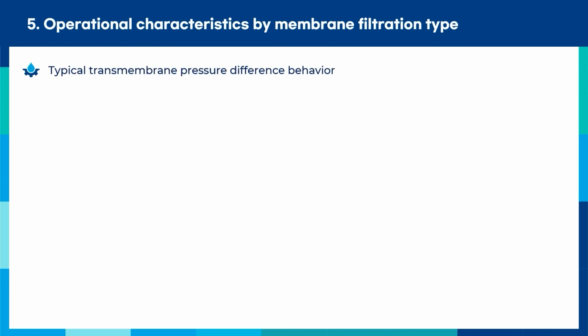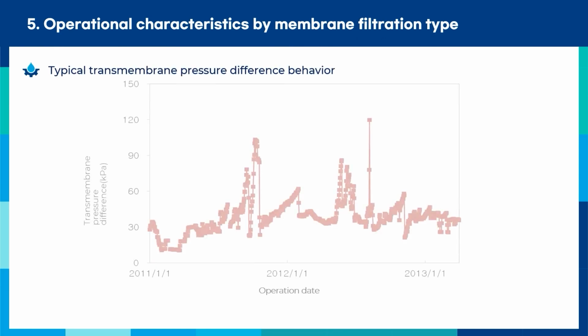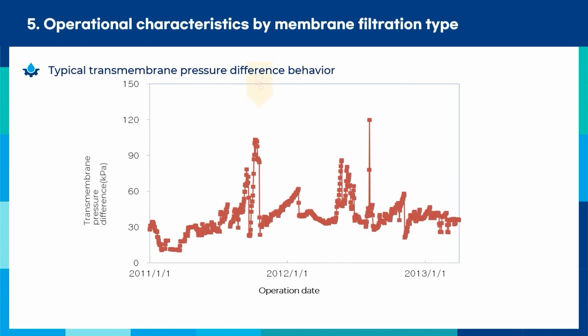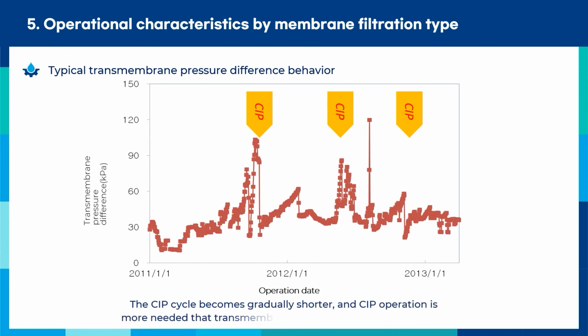Regarding membrane cleaning, there is physical cleaning and chemical cleaning. Fouling substances, which lead to reduced flow rate through a membrane filter or increased differential pressure, can mostly be removed through physical cleaning. However, if it is blocked with material that cannot be removed through repeated cleanings, the material slowly accumulates inside the membrane. In this case, chemical cleaning, also called CIP, must be used to break down or dissolve adhered material with chemicals.